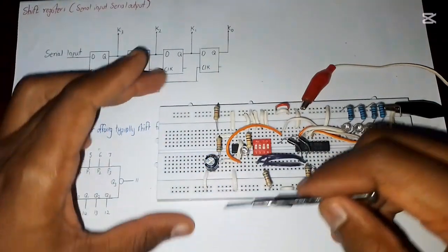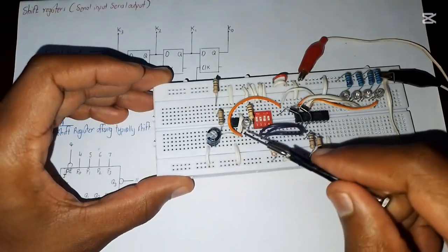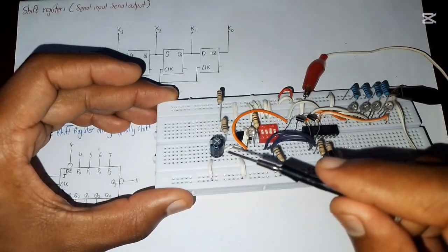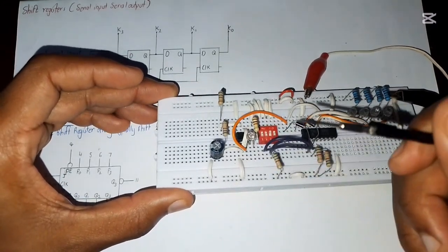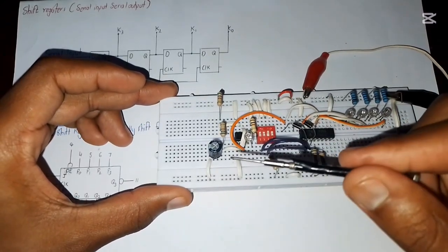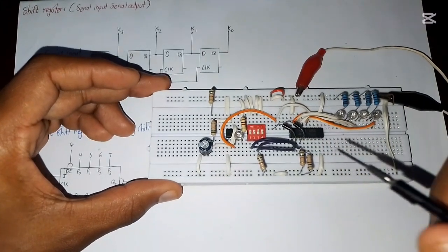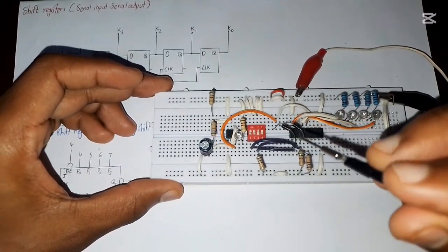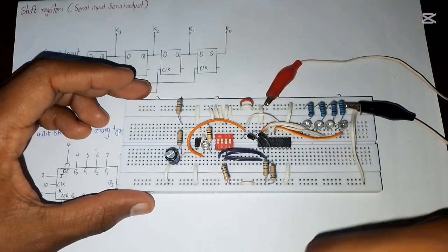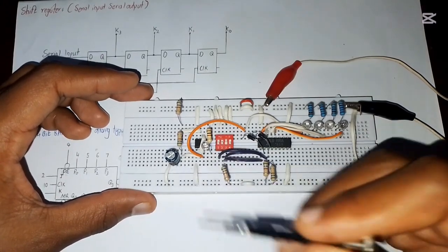So you can see here we have a capacitor that we are using to control the frequency of our oscillations, and I'm using a 220 microfarad. It's quite slow, but as we have said in the previous videos, I'm using it slow for you to understand. I want to show you what happens individually, so you get the concept of what happens inside the circuit. So we have the LED. This is an LED to show you the clock signal.